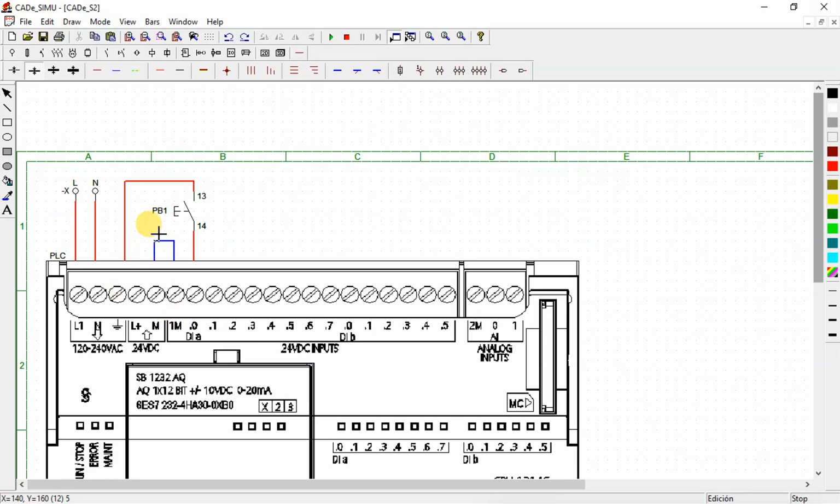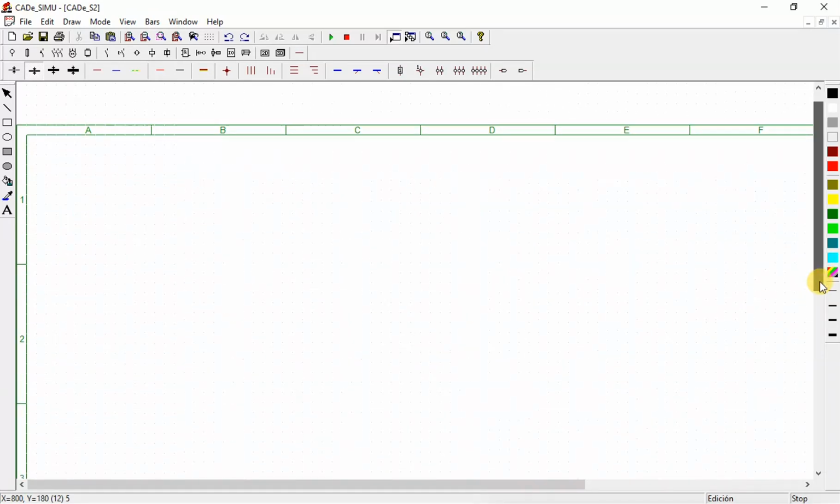But when you give the input buttons a negative, then give the common a live from 24 volts, then the PLC will be sourcing. For more clarification on that, I can make a video in order if you ask in the comments. So for the input, that's how we do it. The 24 volts is for signaling using the push buttons, then this negative we put in the common. All the digital inputs have one common. So that's how we do the input.